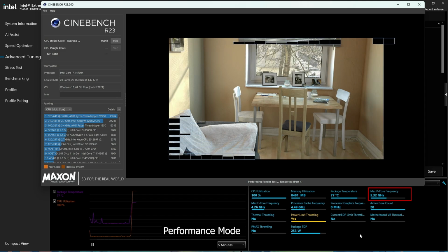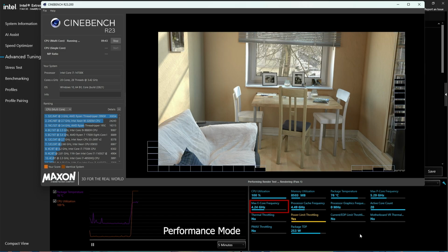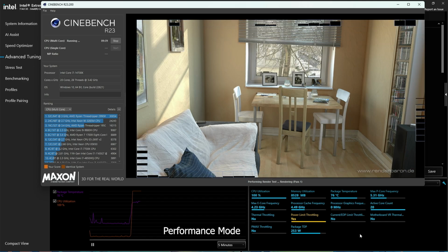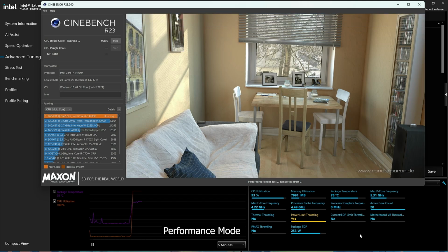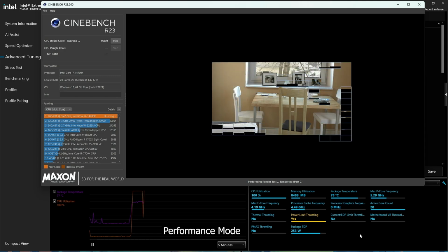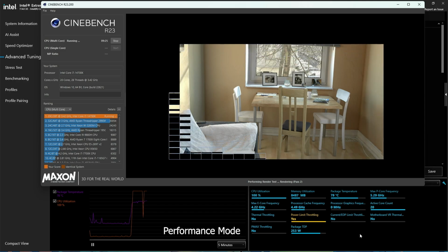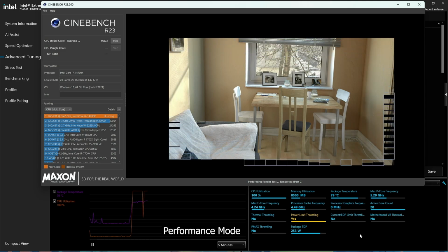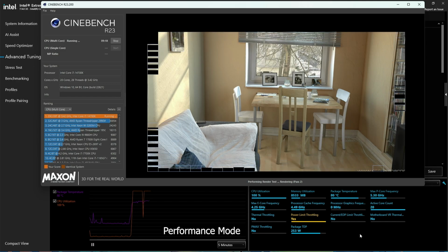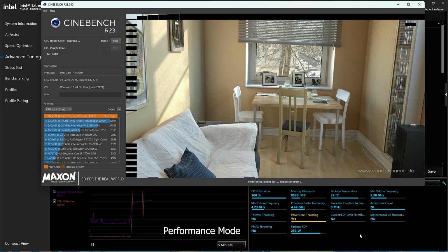It's able to push the P core ratio to 5.3 GHz and the E core to 4.2 GHz, with still the same power draw. The reason for that is the IA, AC and DC combo. That profile is making it reduce the Vcore weight, so it's requesting less voltage for a given ratio, allowing it to push a bit further than the IA DC combo on the BIOS default profile. Also, surprisingly, having LLC at level 4 is able to make it run stable at the same power draw with good temps. So while it's a good customized profile by ASRock, it's still not aligning with the Intel baseline document.